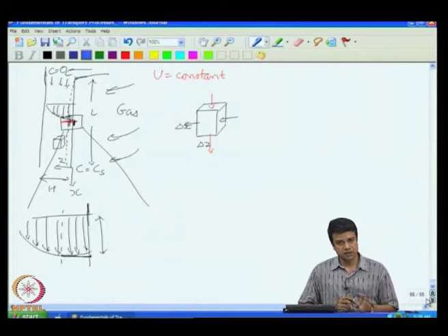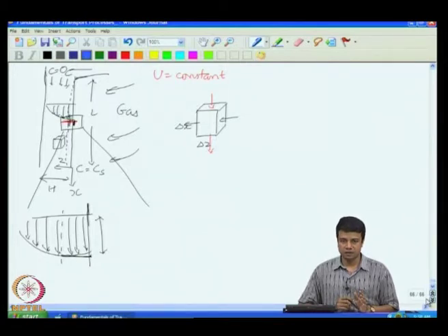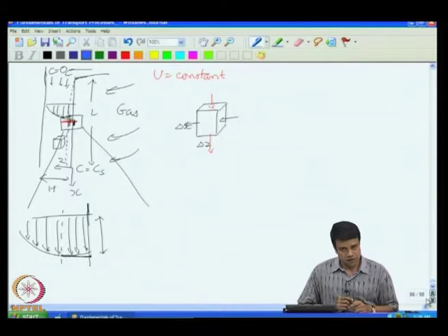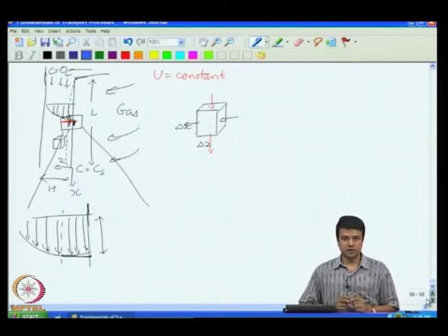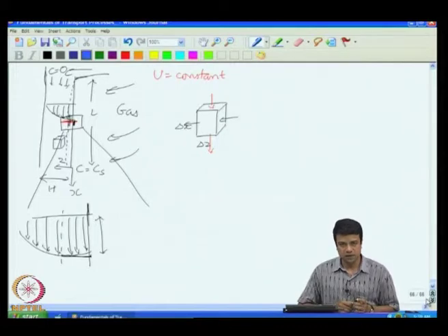This is reminiscent of the assumption that we had made in the previous lecture, that the penetration depth of the temperature, concentration or velocity fields was small compared to the total height h. Except in that case, the penetration depth was a function of time. In this case, the system is at steady state, and you would expect the penetration depth to be a function of the x coordinate.